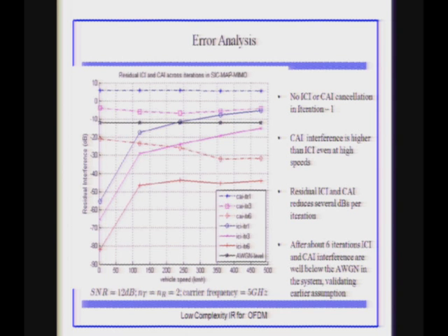So our experimentation is with a 2-antenna case. We did this for the MIMO, and we are talking about a reasonably good SNR, 12 dB, a 2-antenna case, and carrier frequency being that high. And what we are depicting here is the residual interference due to those 2 interferences at different vehicular velocities. To begin with, let us talk about the co-antenna interference.